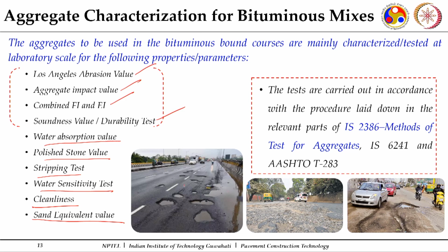not want your surface to have these kinds of things where you are able to see this loss of material, potholes are created. Here you are seeing fines are disintegrated, fines are lost. Again, these are the kinds of situations you want to control. So, you need to check your binder as well as your aggregates to the best of the requirements, the latest